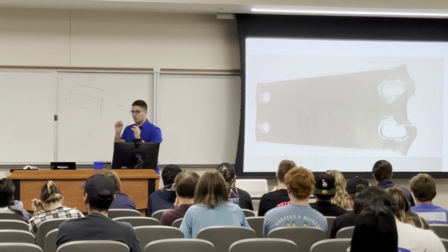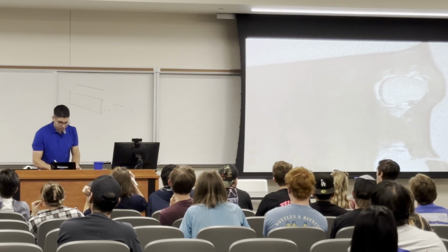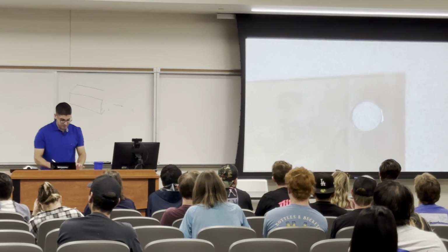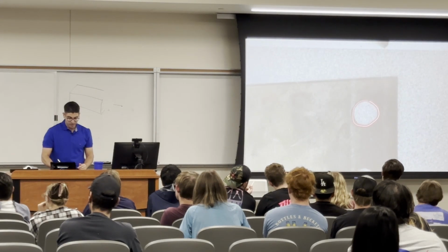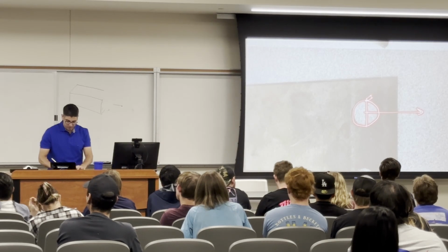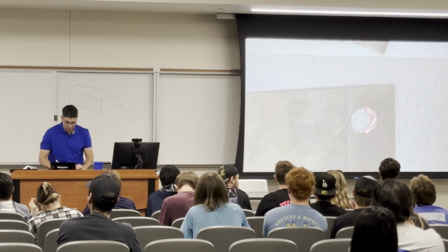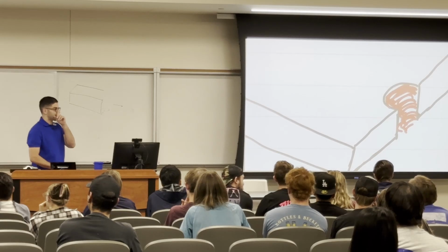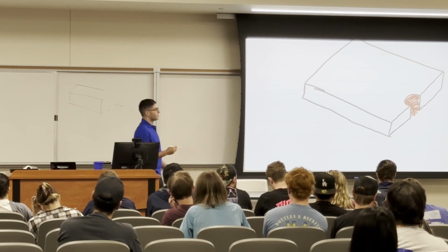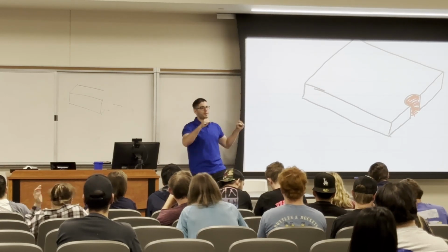The interaction. And it's very small, this area, for example, before it broke like this. If I had a rod here, this is the area that was pressing from the other side. This was the photo before it broke. So the rod was here. If I'm pulling the rod this way, the area that's going to work is starting from here, right? Which is something like this, which was the cross section here. Do you agree that this is the area that resisted the rod? And if we want the plate to not fail, we can increase, for example, the thickness of that area, right? And that's when the rod can resist my weight and not fall with me.